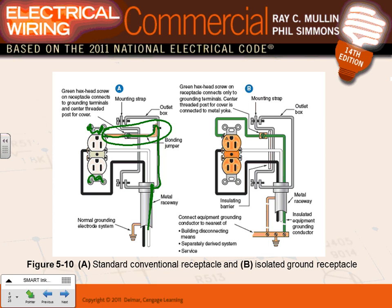Can I have thumbs up? We fully understand how through the conduit we grounded the box. The box is grounded, as well as the frame, the receptacle, and the grounding slot right here. So that's the non-isolated ground receptacle. If you look at the isolated ground receptacle, look at the terminal here. The grounding slot is actually grounded through an insulated equipment grounding conductor that goes all the way to the building disconnect, the separately derived system, or the service. So they take a conductor.